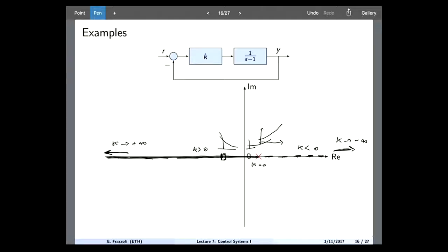I will keep moving the closed loop poles to the left, meaning that my system will be stable, but also a faster response. Okay? Going back to the cabin example. Essentially, the more aggressive you are in setting the temperature control, the faster you will converge to your desired temperature. On the other hand, and this is another thing that I guarantee you will make at least once in your career.